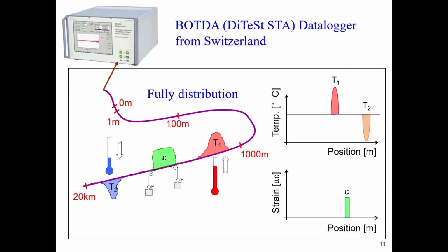Okay. So this is based on Brillouin scattering, and we bought this instrument from Switzerland. For example, imagine we have big pipelines. You worry about pipeline defects or cracks, whatever. You can glue the fiber line on the pipes. Pipes are normally very long, right? This technology is good for larger structures. Then any strain or temperature change, the instrument can read. It can be a few, even tens of kilometers, for a large, long-distance structure.